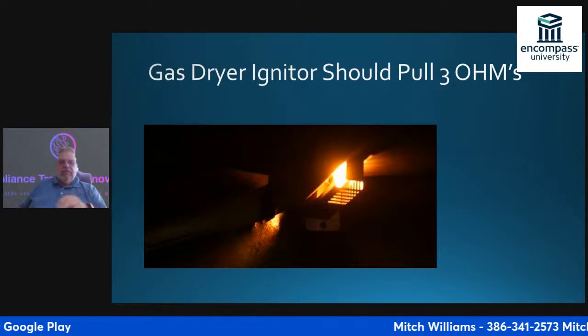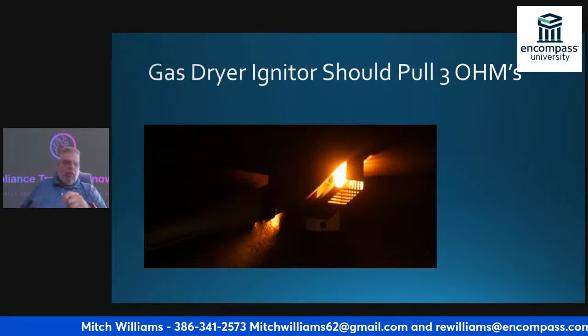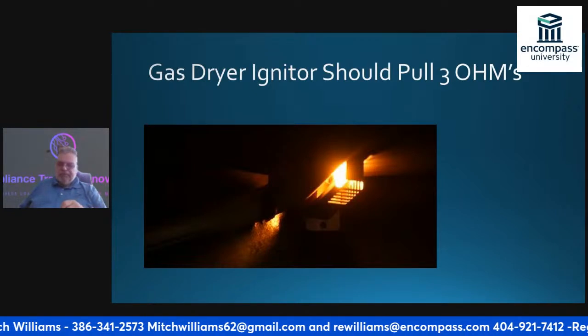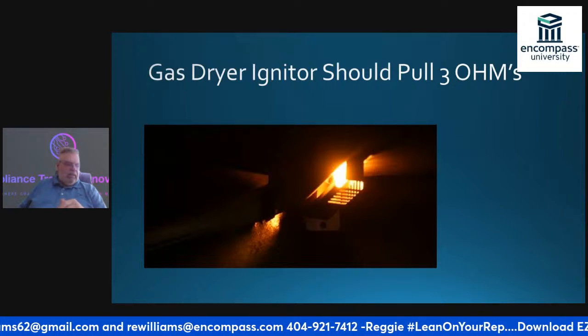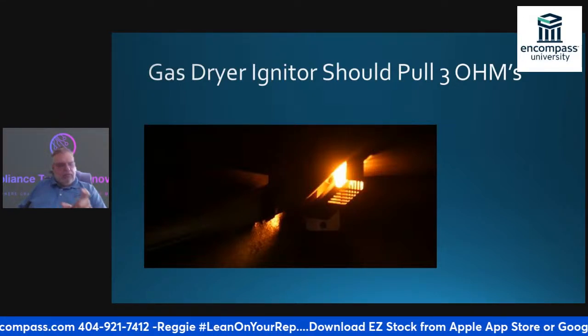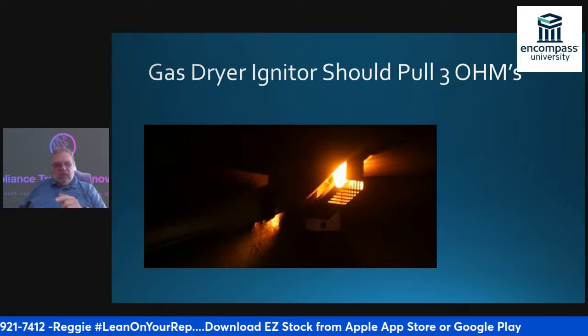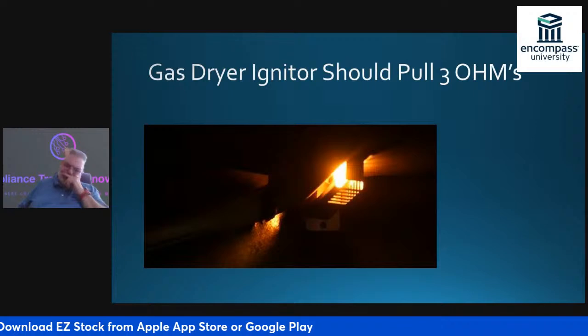I need to ohm those 2 connectors out, going across and going to the lowest scale, or you can go down to the continuity where it buzzes. On the gas dryer valve, I can go between those 2 terminals, and I should get a beeping sound.